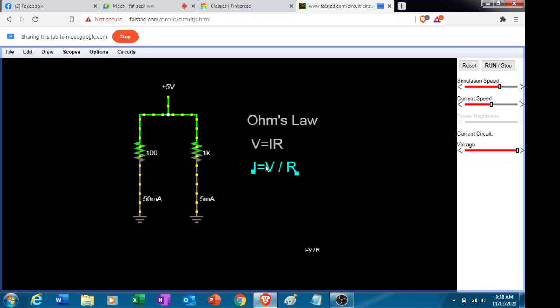Since current is inversely proportional, that is actually the explanation now. Why is it that there is more current in the left side as compared to the right side? Because of the inverse proportionality. Do you know what is meant by inverse proportionality? Yes, sir. Okay, so the lesser the resistance, the bigger the current. The bigger the resistance, the lesser the current. So we're talking about resistance.